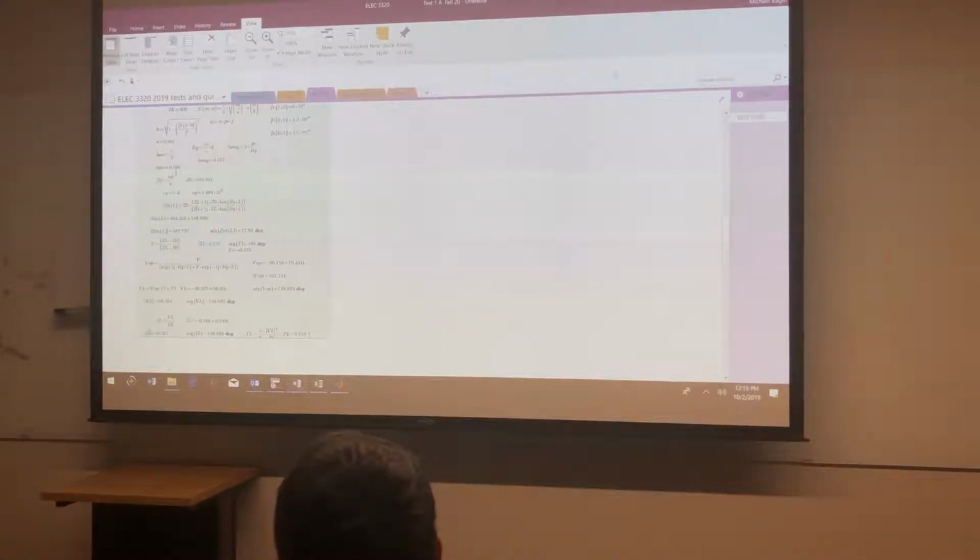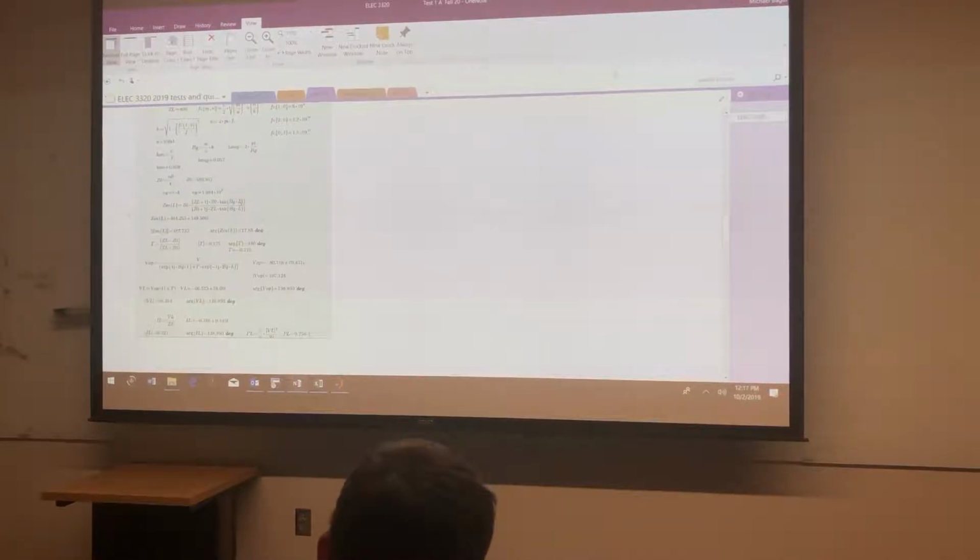After I have that, next thing I get is the input impedance. Now, ZL is given, right? And I gave you this formula, by the way. I wanted to make sure that I said I'd give it to you. The only thing you had to make sure is beta in the guide goes here and the length of the guide goes here. And that's the formula. It's just plug and chug. A lot of people, believe it or not, put in ZL here, now for Z naught. In other words, they mixed them up. I'm not sure why. The only thing I can think of is probably exhaustion.